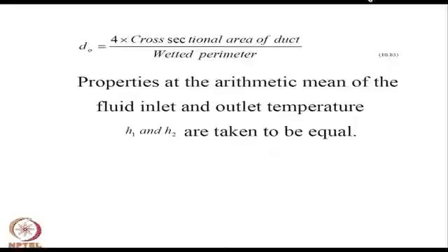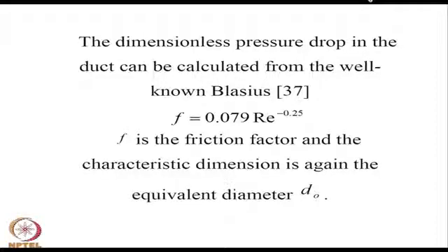Now, we come to a more important thing. First, we are considering the air heaters vis-a-vis liquid heaters. The advantage for the air heater is in the direct application of hot air, which the solar is likely to meet very conveniently, because very high temperatures are not required. Something like 40 to 60, 70 degrees centigrade is good enough for quite a few applications.